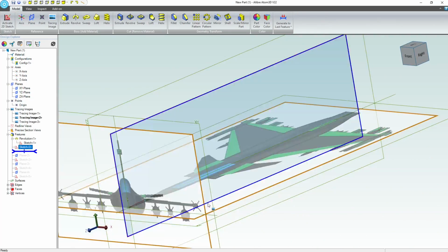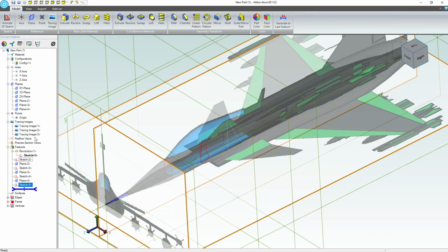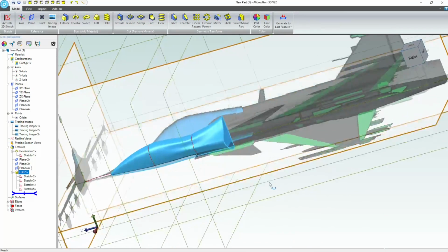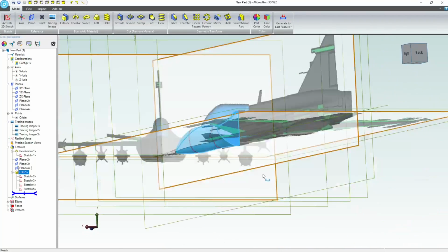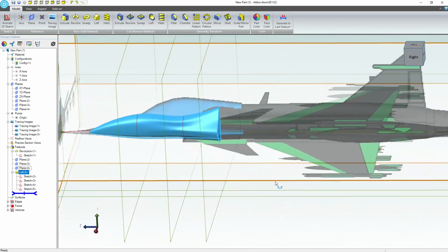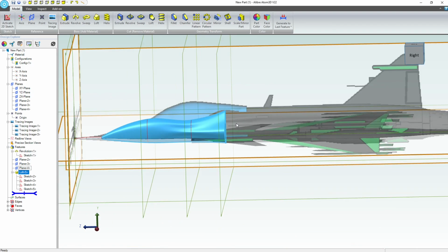And so if we get that started, I'm just going to do a preliminary loft to make sure that nothing looks crazy. We'll generate to last feature, and we'll choose loft, and we can see we started out with sketch 5. Let's actually clear all and start out with sketch 2, 3, and I can choose from the graphics display here 4 and 5, and if I say OK, then you can kind of see what our body is looking like, and it actually seems to be matching pretty well. You know, whenever you make something for the second time, it always goes smoother. So once we start adding profiles here, then this is going to start coming up, and we'll recognize that local minimum and things. So this is looking great.